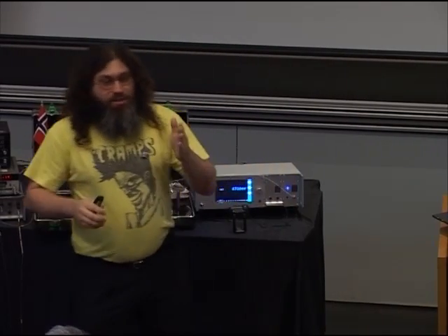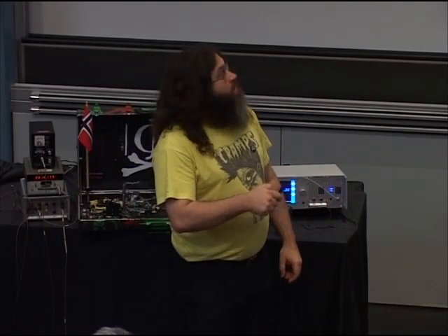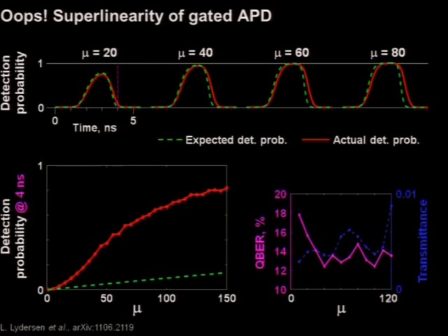First, we attenuated this narrow pulse to a single photon level, about 1 photon per pulse, and measured the sensitivity. And then we model what happens when the number of photons per pulse is increased to 20, 40, 60, and 80 photons per pulse, assuming that each of those multiple photons is detected independently in the detector. So the probabilities add up to the total detection probability independently, based on the measured single photon sensitivity. And this is the green sensitivity curve, the theoretical calculation, assuming independent detection of multiple photons.